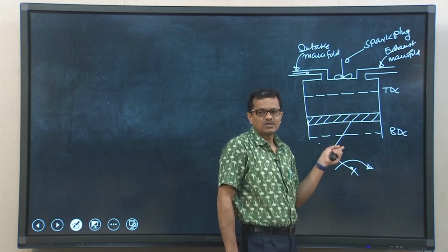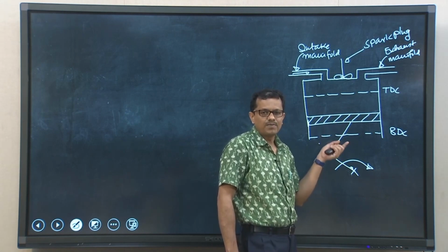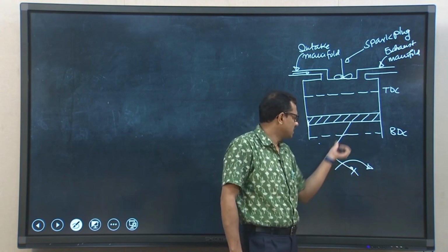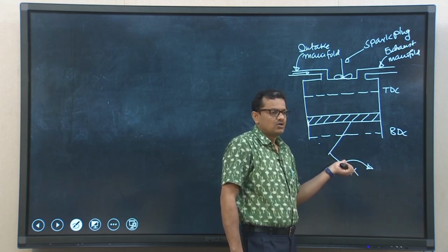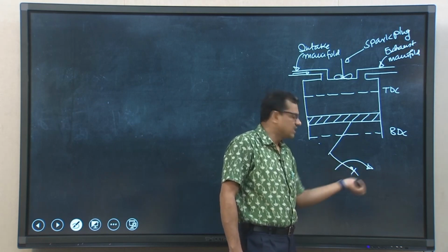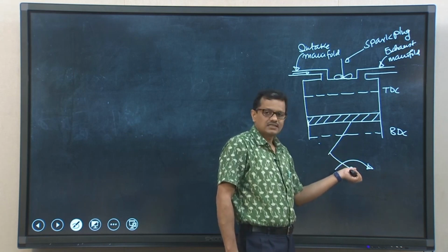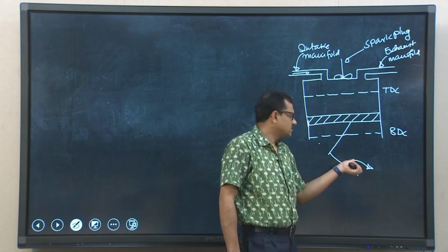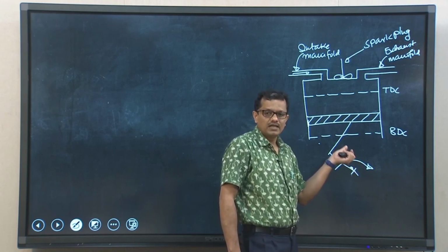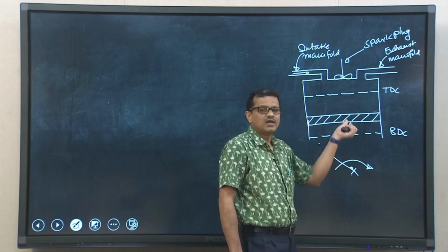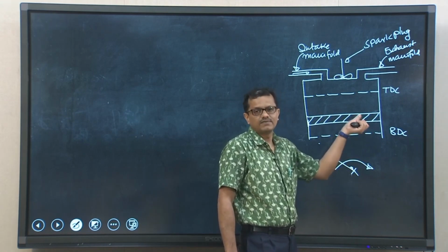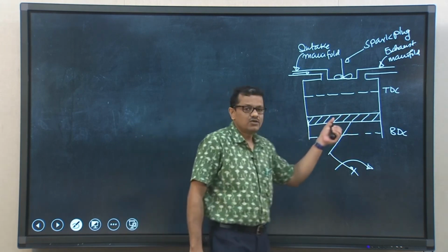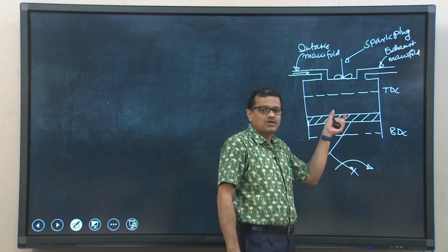And since the movement of the piston is spontaneous, the power we get during the power stroke will remain stored in the flywheel, because this is the crank and this is the connecting rod. So, that crank will be rotating, and the flywheel is connected to the crankshaft, and that crankshaft will again borrow energy from the flywheel for the movement of the piston between TDC and BDC during the 3 different idle strokes.